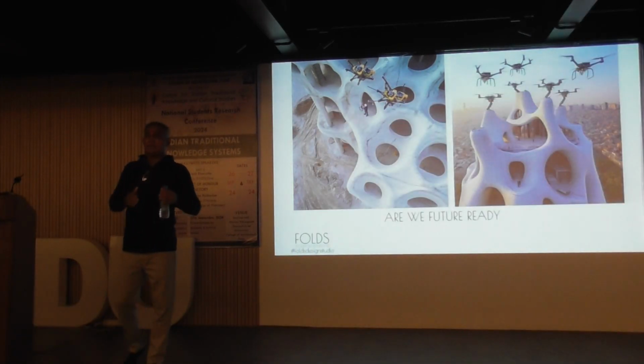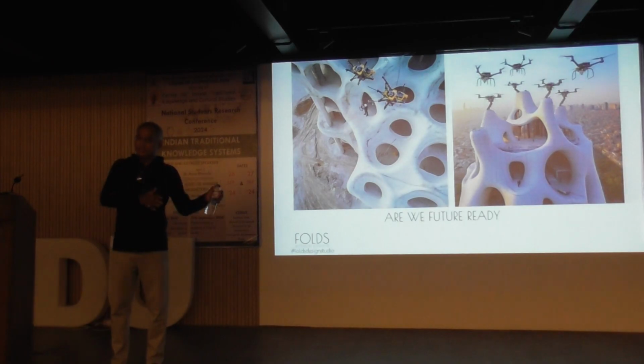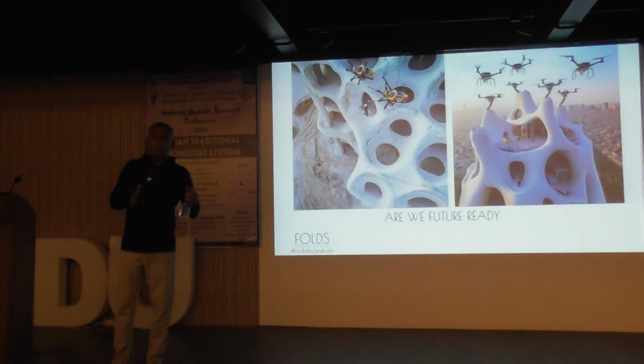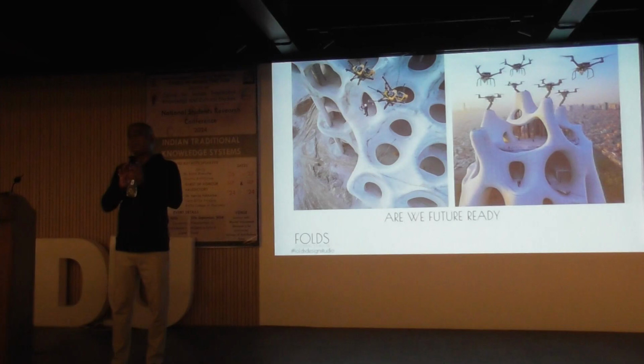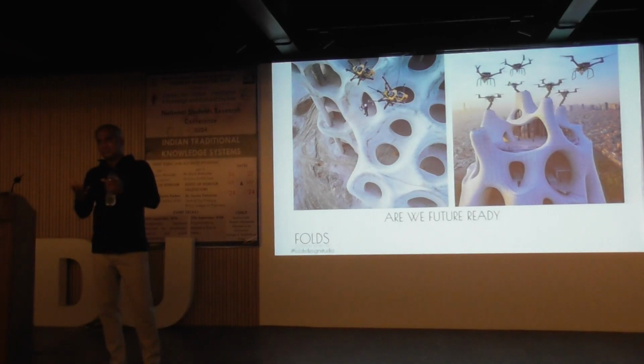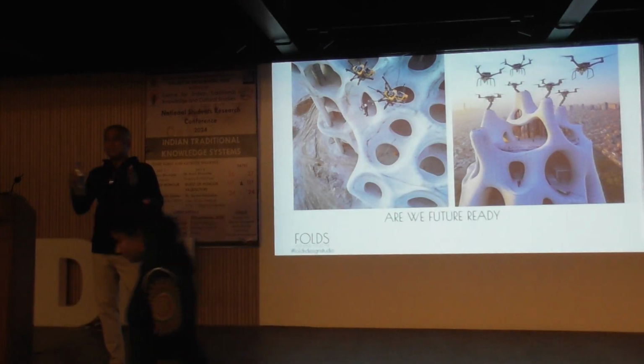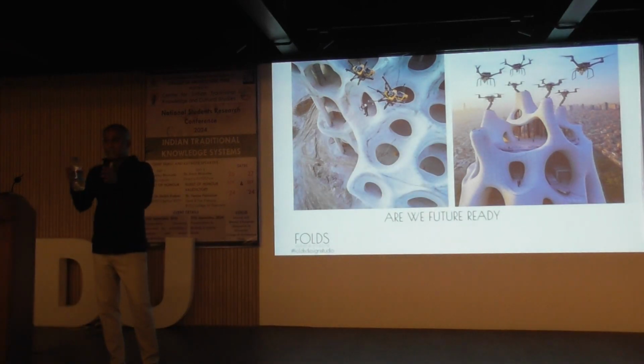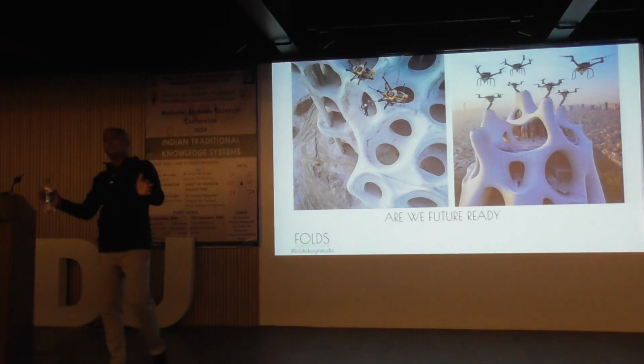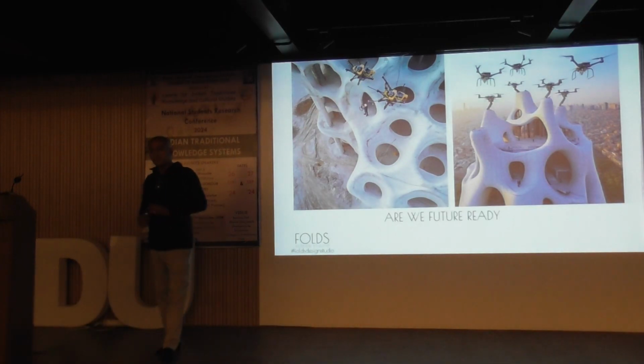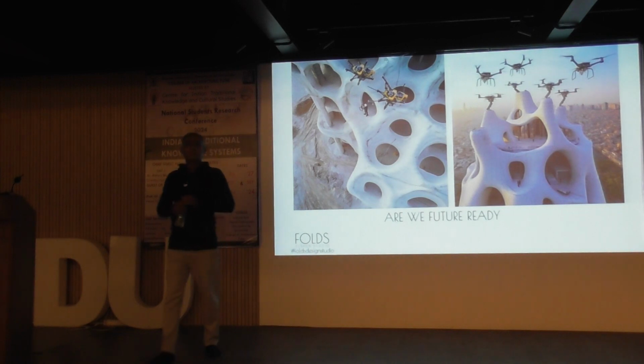But in India, I, as an architect who is practicing this kind of design detail today, am using 3D printing only for my outer shells, so that I can cast my material inside. The way centering is done, after casting the columns we put centering. Instead of that steel centering, I am using 3D print models and getting my design. Okay.